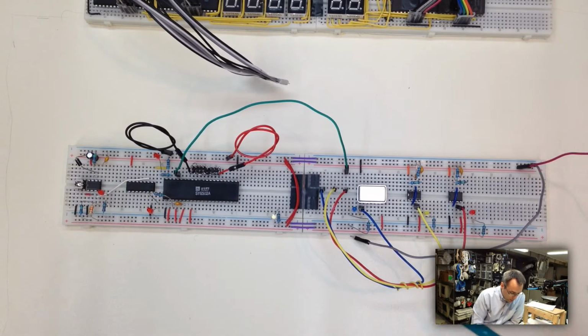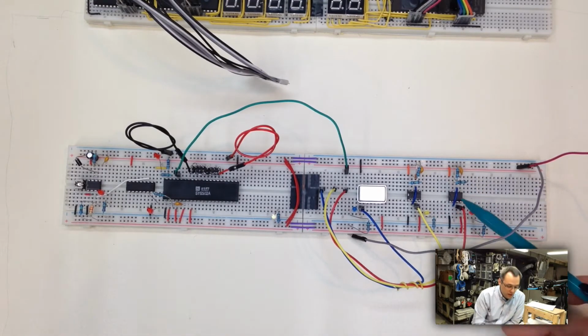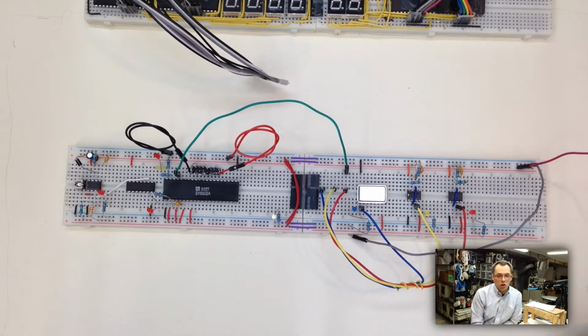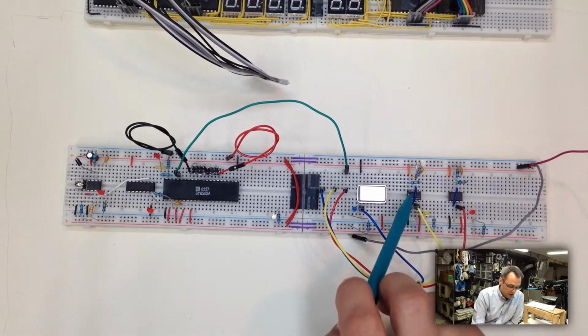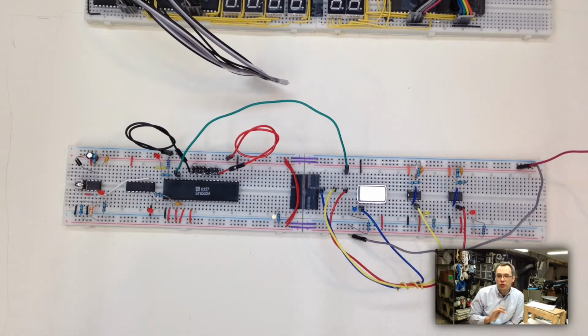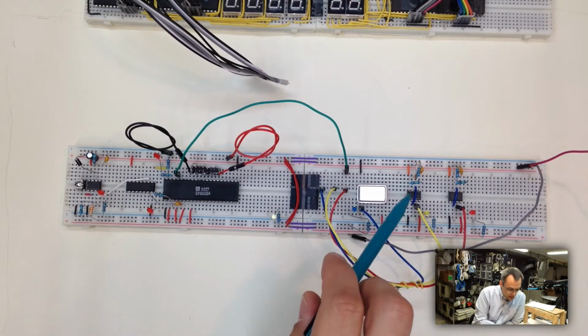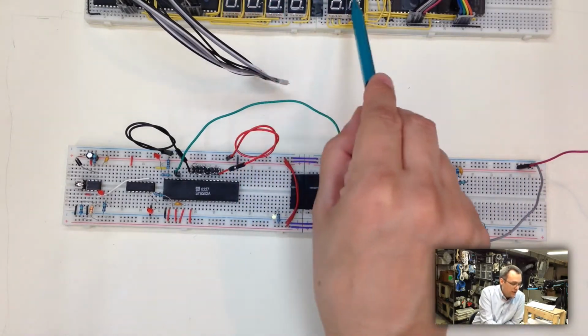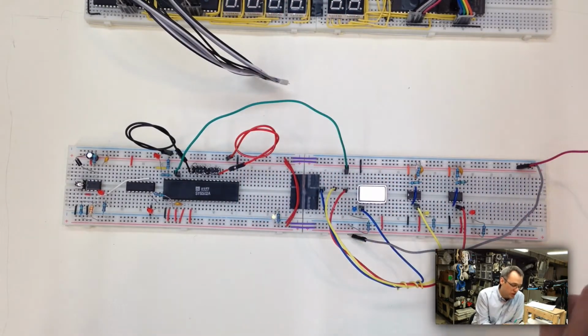Of course, we have our red output coming over here. And we also have an LED in series with that, so that we can see that it's cycling and that this oscillator is actually functioning. This oscillator is our slow oscillator, this being super slow. This oscillates at about 150 hertz, give or take, 145, somewhere in there. Basically, this allows us to run the clock fast-ish, but still slow enough that we can actually see something happening on the computer. So if we want to speed up operation during diagnostics.